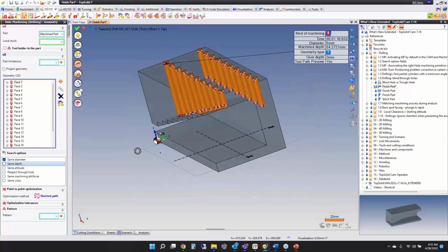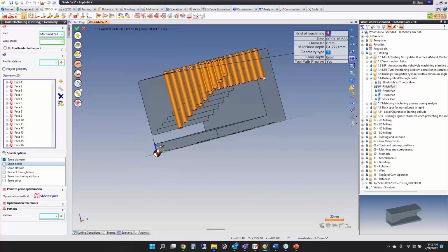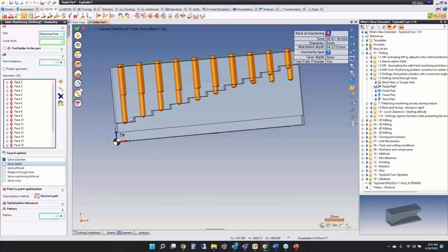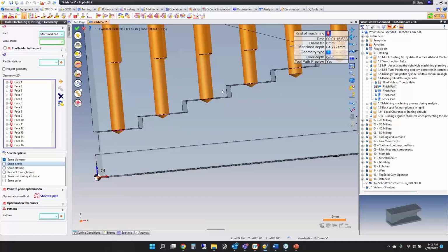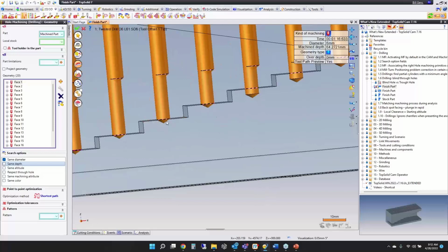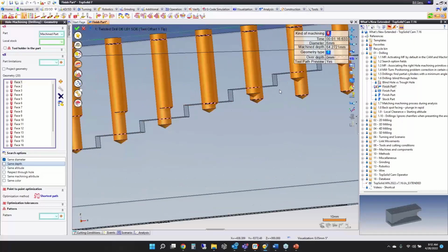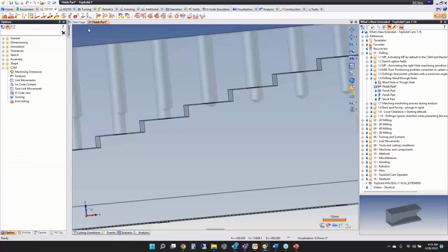And now we look at this. All my standard blind holes that are back there, of course, are correct. And now if we look at these, going up the stair steps, again, that was 10, 15 millimeters, 20, 25. All of those are being held back, but then the rest of these are getting an appropriate through drill. So again, the goal here is just to give you a control on the underside of the hole where you're breaking through to check against faces that are considered finish faces that you might have otherwise potentially collided with based on your drilling overlength. And even if you type a bigger drilling overlength in, these will always be protected. Cool.